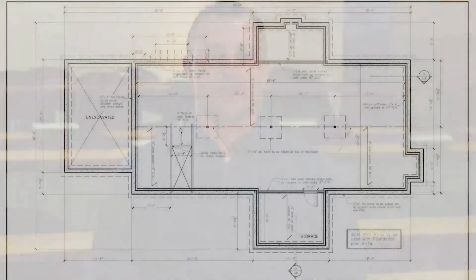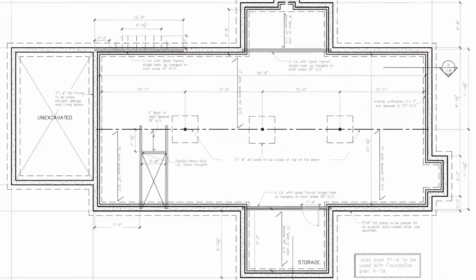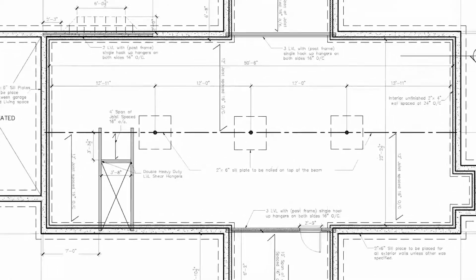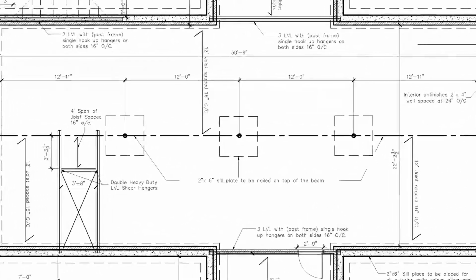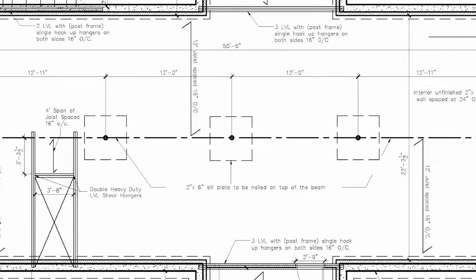Joists. Joists are prefabricated wooden I-beams, typically not bigger than 3.5 inches in width. The web of the joist can vary in height, but these plans are scheduled for 9.5 inch that are perpendicular to the steel beam. More specifically, the direction of the joist will be depicted in the plan as such.